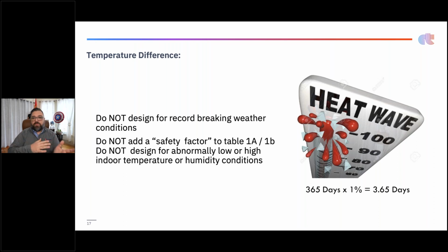It allows room for drift, and we do the same thing on the heating side too, where we actually heat to 70 degrees plus or minus 2. That's what's in the code. It goes as high as 72, as low as 68. And if it's really cold out, furnaces or the boiler or the heat pump's going to run all the time, and it's going to start to dry out the air. To feel more comfortable, we can add humidity, right? And most furnaces I know in the Northeast and the Northwest typically have whole home humidifiers on them because of this, in order to provide that comfort.